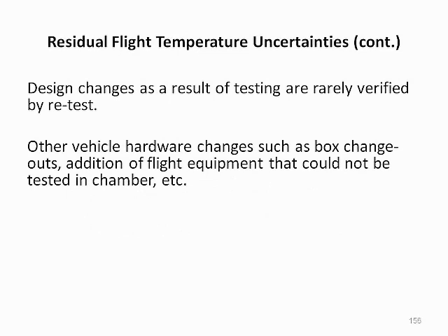Also contributing to residual uncertainty is the unfortunate fact that the thermal design changes that sometimes result from testing are rarely verified by retest due to cost and schedule pressures. Other routine vehicle hardware changes such as box changeouts and addition of flight equipment that could not be tested in the chamber also add uncertainty.